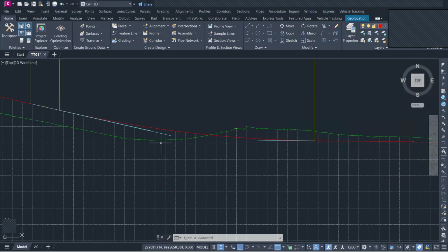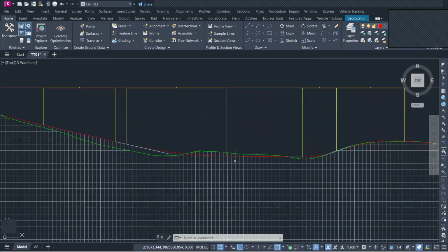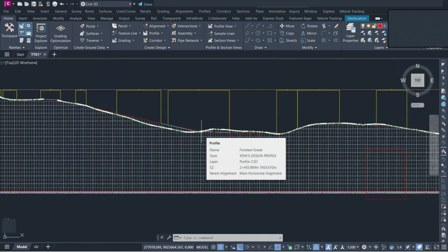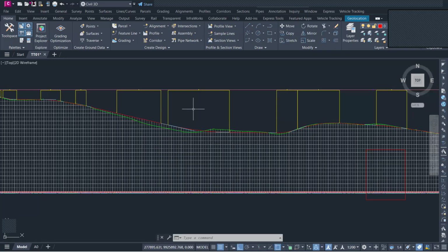Now, someone talked about an important aspect, the culvert. And now, when you're positioning a culvert and a bridge, you already have the design and the specifications. So let's say, for example, you have a culvert of 900 millimeters. So that means you need to have a picture in mind of how the typical cross section of a culvert looks like. So you'll need to have a bed of 50 mm below it. Then at that point, you have the ring of the culvert. That is the thickness of the ring. So sometimes it's 200 mm. And then after that, you will have the diameter. Remember, the diameter you measure internally.